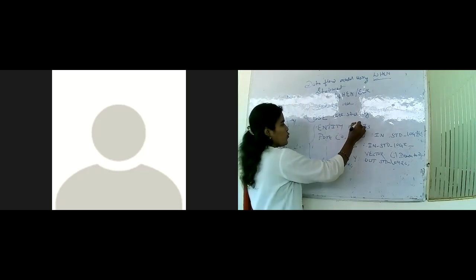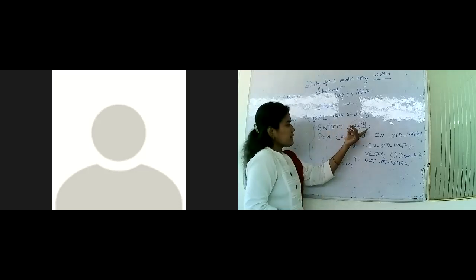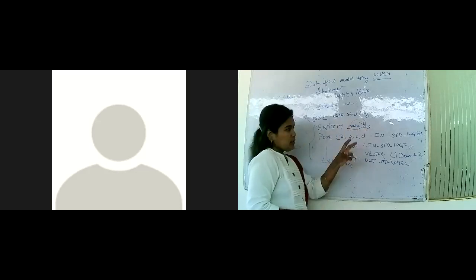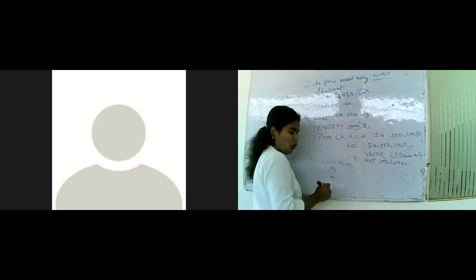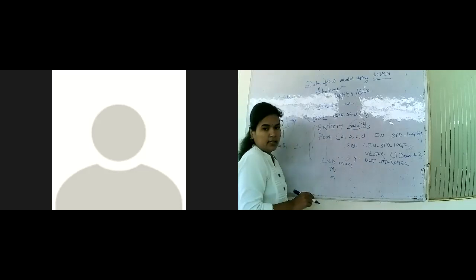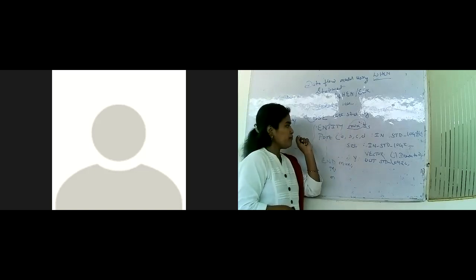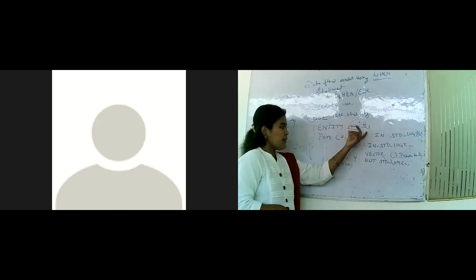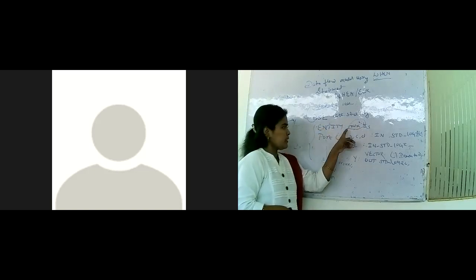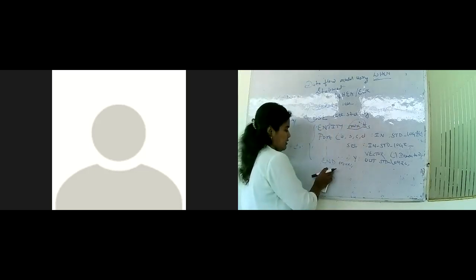If I am taking the name as 4:1 multiplexer, then you have to end with the 4:1 multiplexer name. Whatever name you write here, the name should be the same. If you use a capital M here and a small m there, there will be an error in VHDL. So you have to use the same spelling and the same case, upper case and lower case. So it is entity mux is, and end mux, the end of the entity.